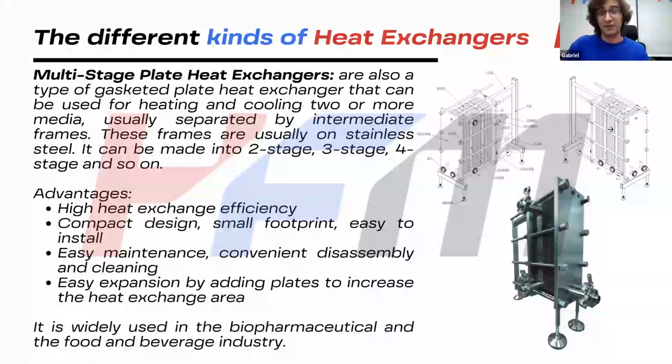So they are very highly efficient. They are very compact in comparison to other heat exchangers, such as the shell and tube heat exchanger. But we're not going to be talking about them today, okay? It's just for you to have an idea about how they work. They are very easy to maintain, and convenient to assemble and disassemble as well, because it's just like making a puzzle. We can assemble the plates together, and we can even customize the area, increase or decrease the heat exchange area in order to achieve the right temperature you're looking for. So they're very handy from this perspective, with very easy maintenance and very easy installation.